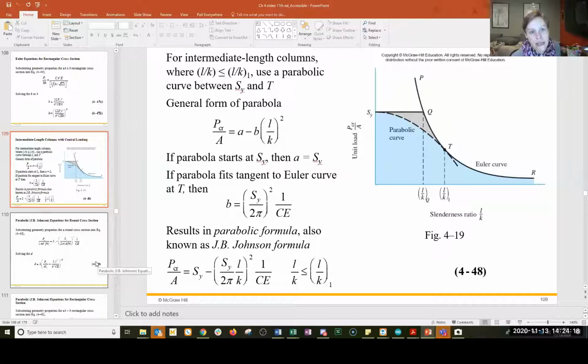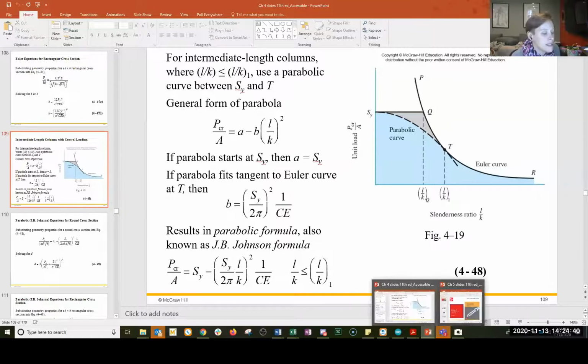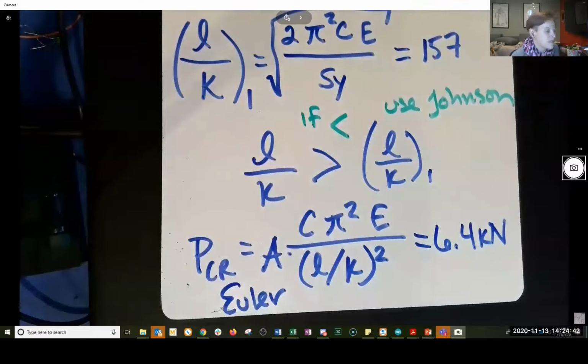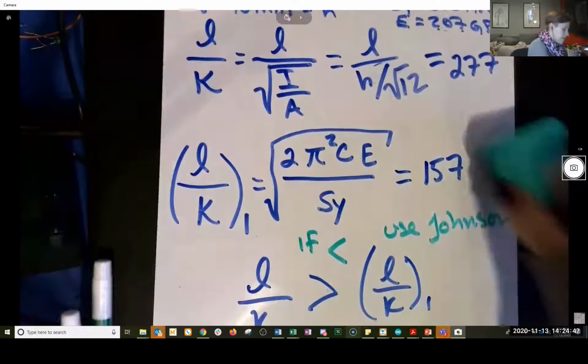Yes, Ryan, exactly. In buckling, we could certainly say P critical over area is the axial stress, but because it's in terms of that critical load, we'll just directly apply the critical load to see the factor of safety. That didn't come out in super clear English, so let's just do it.